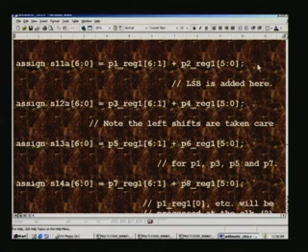This is the LSB addition, and this 0 we should not forget to add at a later stage. So remember that the P1 reg 1 0 bit, which has not been accounted for here, will have to be accounted for later on. This LSB is added here, and note the left shifts are taken care of, as we have described here. We have S11 through S14 doing precisely the same set of operations, but on different partial products: P1 P2 here, and P3 P4, 5 6, 7 8 here.